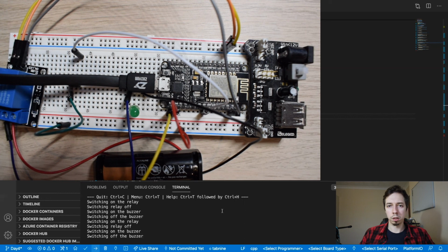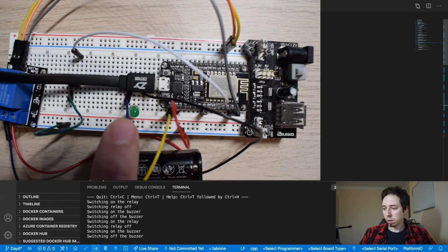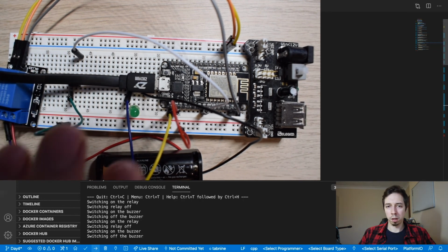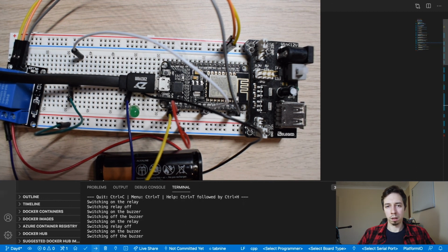Okay, so the initial test is working with the serial monitor, and now I'm going to connect the external power source, and let's see if the diode goes on. And also, I'm going to connect the buzzer, because now we're basically sure this is on D2. Right, so I'm gonna connect the buzzer to D2, and yeah, let's just test it with the low voltage circuit on the diode. However, once this is working, I'm gonna connect the cable that is gonna be used with the coffee maker.